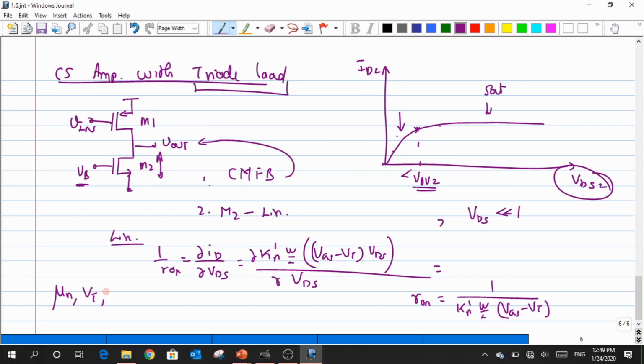This 20K is very difficult to control just because over this entire die the Kn' parameter will vary. So there is no control for me to define an appropriate value of Ron in the circuitry. Does that make sense? Ron depends on the process parameter. Because of this dependency, fixing Ron to a particular value is a bit harder.